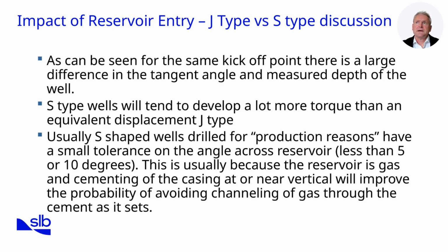However, the trade-off is mechanical. Drop sections create high side forces on the BHA, increasing shocks, vibrations, and wear. Torque and drag are also higher, sometimes limiting the ability to reach TD.